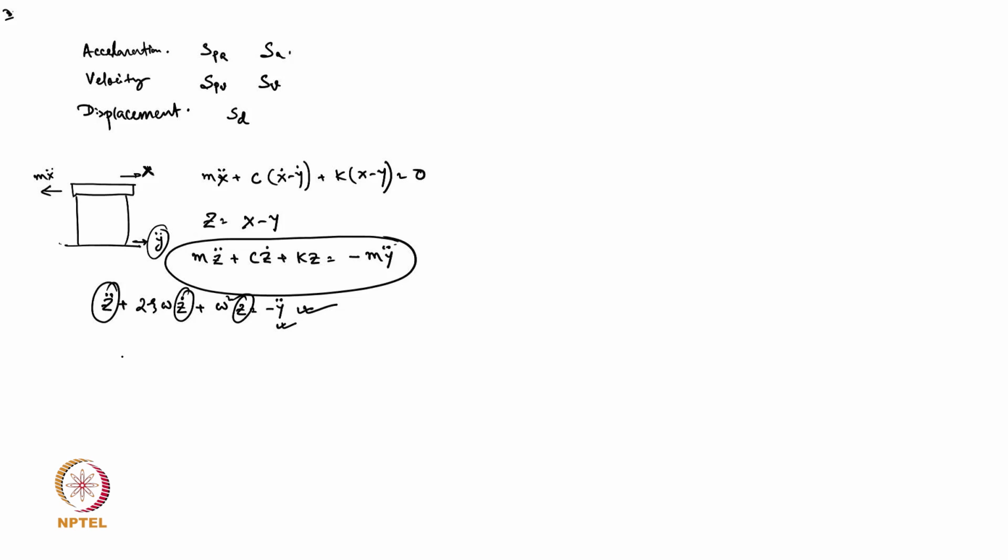Perfect. So we can say that z is primarily a function of xi and omega for a particular y double dot, because y double dot is a signal. It may be earthquake, it may be wind, whatever it could be, or maybe some machine is running, so that machine signal. And z is the relative displacement of the structure from the base.